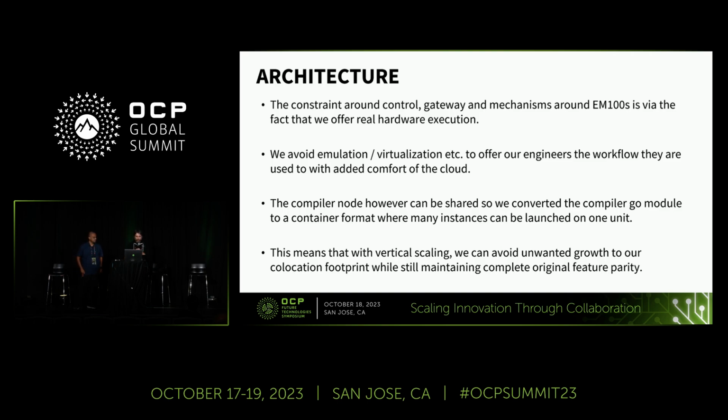So I spoke about the architecture, but the magic behind it is based on the fact that we are using Flash emulators. So if you want us to integrate some hardware within one of the OCP experience centers, we'll be needing to modify the hardware, or you will be needing to send us hardware with the pin headers on the SPI interface, including the BMC and the ROM.